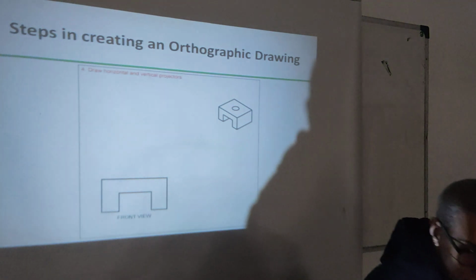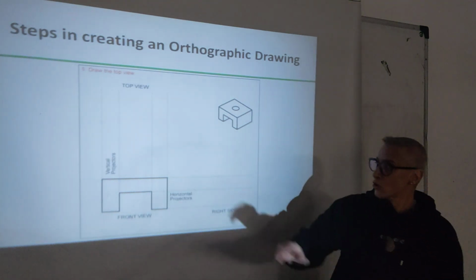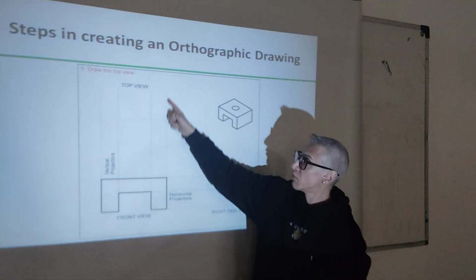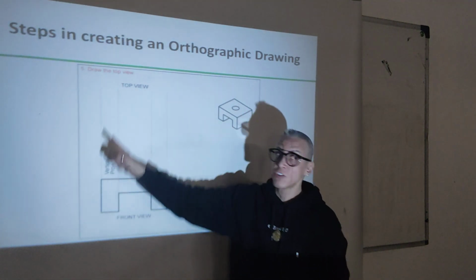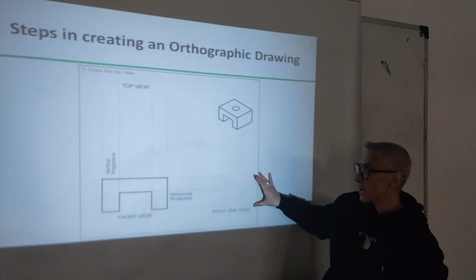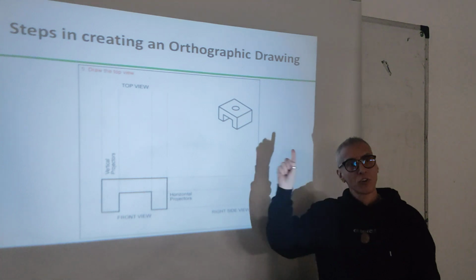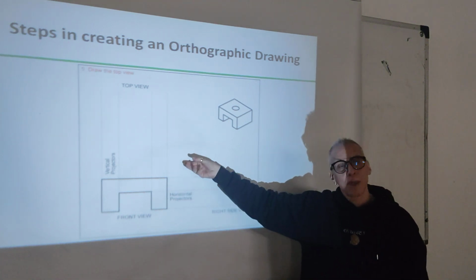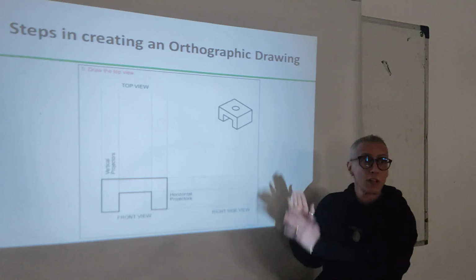Great. When you draw the front view, it must of course perfectly align with all the other views. These extension lines you draw to make sure everything aligns. Be careful, go back to the rules to know the line type, where you need to leave space and where you don't, so that the drawing is perfect.